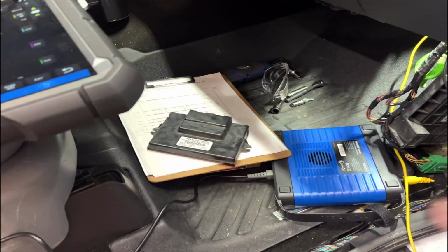Well, sometimes things just don't make 100% sense. Let me show you what we got going on here. We have replaced the transfer case control module. We have not replaced or even plugged in the four-wheel drive motor assembly, and the truck seems to be fixed. Let me show you. Old module. New module, just kind of drug out of the way. Our scope lead is on our position return, which always had 12 volts on it before.